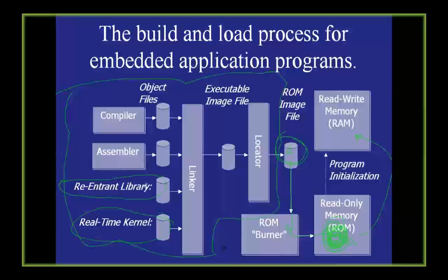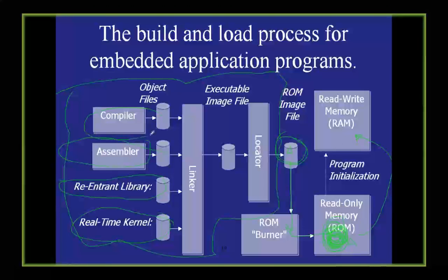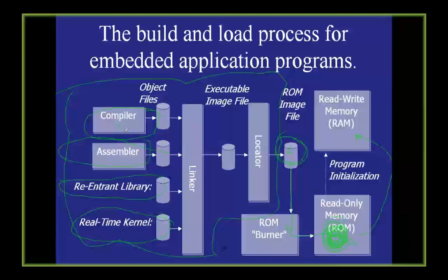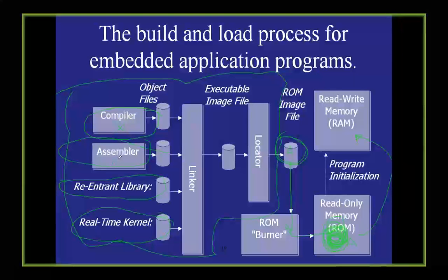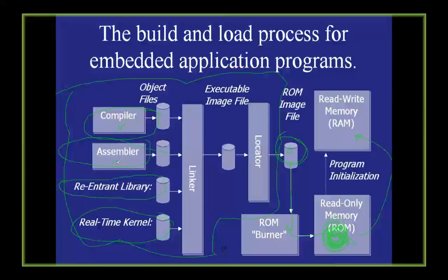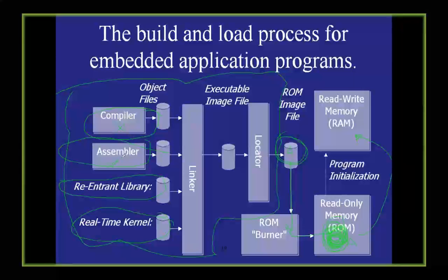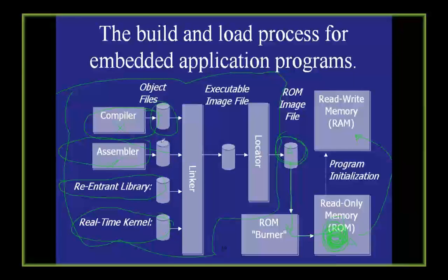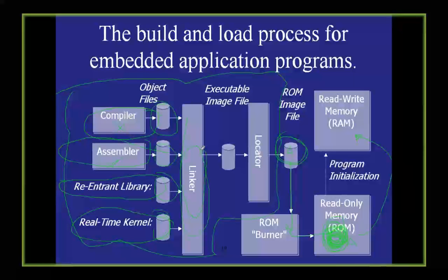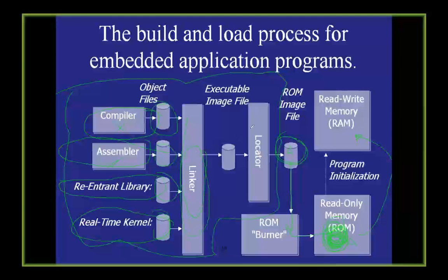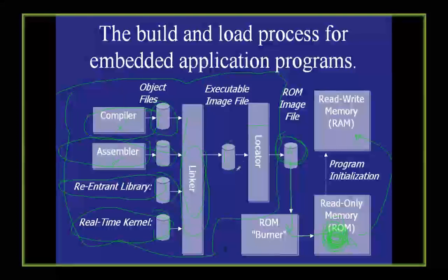Then they may provide some library support which is unique to your applications, and some tools like assembler and compiler. These are cross compilers and cross toolchains. I would say cross compiler and assembler; we don't say cross assembler, since an assembler generates architecture-specific code anyway. All the intermediate files which are created over here get clubbed together, and we write a linker script. A linker script is also called a scatter file. It's usually a small piece of information which lets you say what part of the program will be placed where. So the linker connects that program and creates an exe.